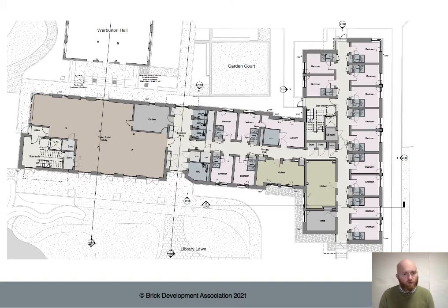You can see the openings at this level, but actually, are there panels of brickwork above those openings? Does the entrance, the recess for the opening, continue all the way up, or does that just stop at ground floor and you have a different scenario at the second floor or the spandrel zone in between those floors? So for the sake of argument, we can't see the detailed dimensions on here, but we'll run through it and you should hopefully get a rough understanding of how to approach the setting out of movement joints.